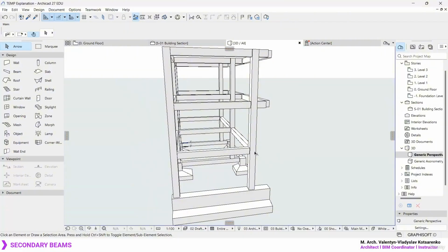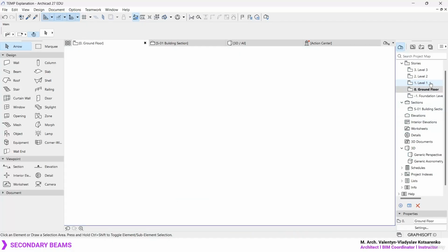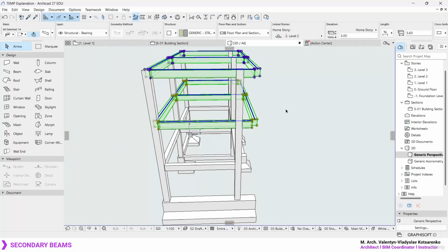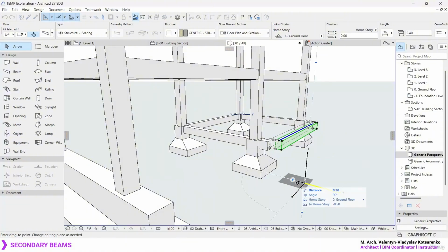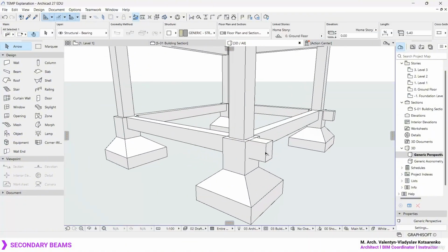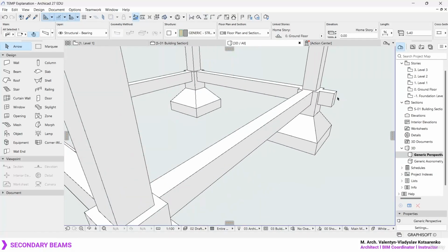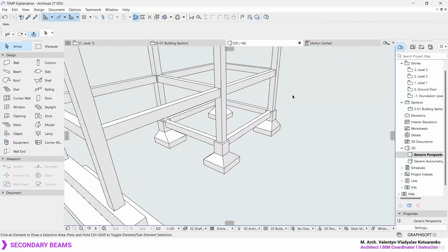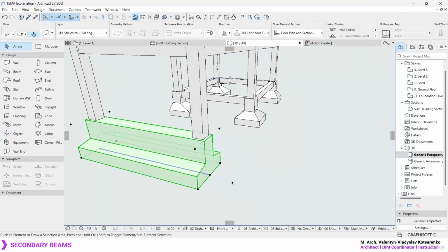But if you notice, it has adjusted the columns, so we also need to repeat the same process with the other types of beams. For this case, what I'm going to do is maybe I'll select everything, simply delete this, move this footing 1 meter over here, and move this element also 1 meter over here, and adjust this element 1 meter, okay? Also click on the reference line, 1 minus, and it's going to adjust automatically for you, okay? Once again, 1 minus, and we adjust the structure.